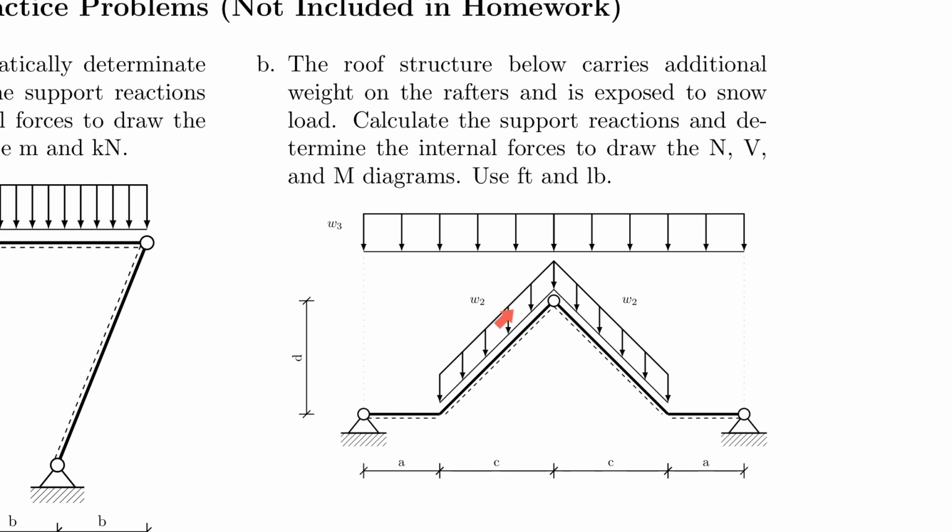First of all, we have a superimposed load case. We have self-weight here, and then we have snow load on top of it. But we also have a non-right-angled corner that has no hinge in it. You have not seen this so far in this class. We only had corners like here that had a hinge and were not orthogonal. What this means is that the shear force and the normal force at the corner need to be translated under the given angle. Whatever angle these values give you, C and D produce a certain angle to the horizontal, and that leads to a transmission of the shear force and the normal force at that corner.